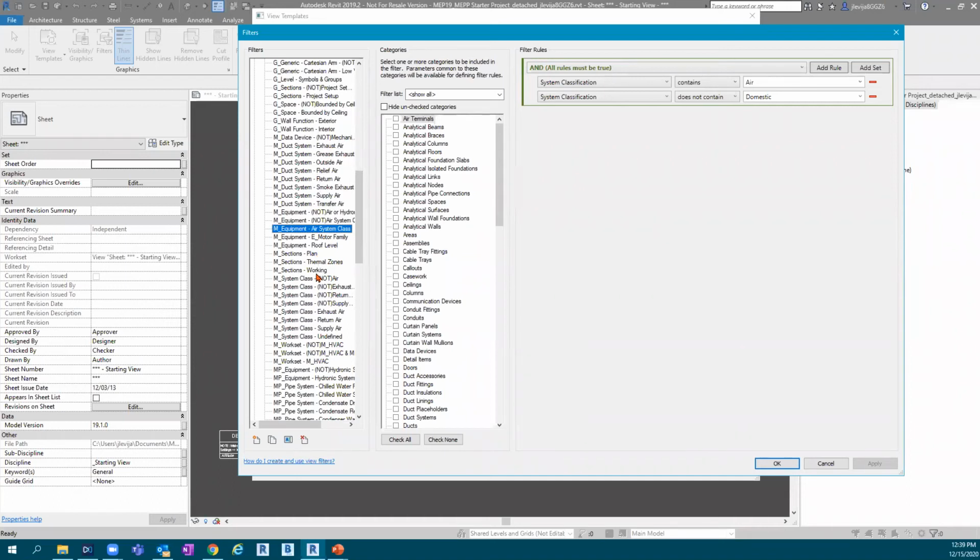Traditionally, what I was used to seeing is we focus on the systems for our filters, and that's about the extent of what we see, and we drive some of that with work sets. Well, the MEP3 allows us to drive systems with multiple filters in place of work sets, giving us a little more flexibility and more in-depth view options as well.